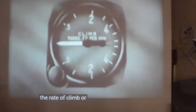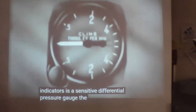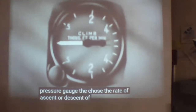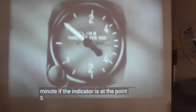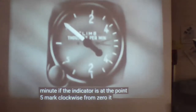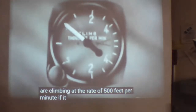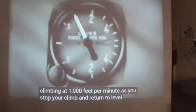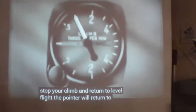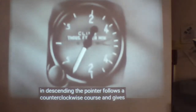The rate of climb, or vertical speed indicator, is essentially a differential pressure gauge. It shows the rate of ascent or descent of a plane in feet per minute. If the indicator is at the 0.5 mark clockwise from zero, it means you are climbing at the rate of 500 feet per minute. If it is at the 1 mark, you are climbing at 1,000 feet per minute. As you stop your climb and return to level flight, the pointer will return to zero. In descending, the pointer follows a counterclockwise course and gives the rate of descent.